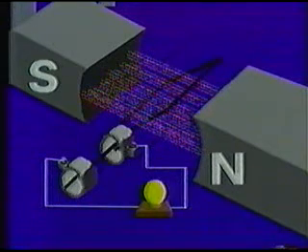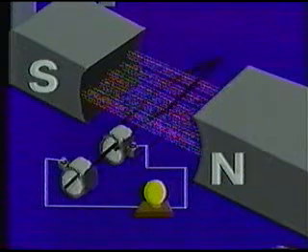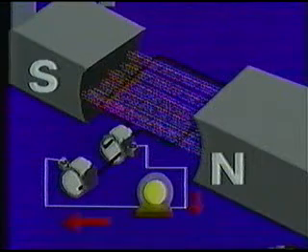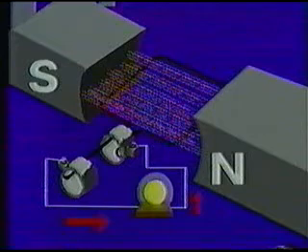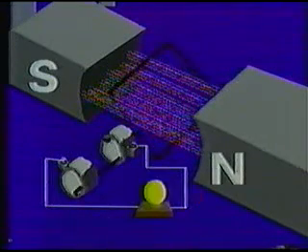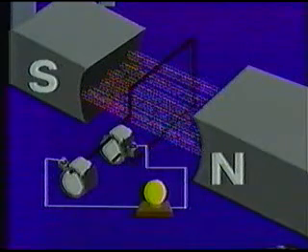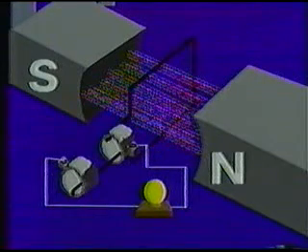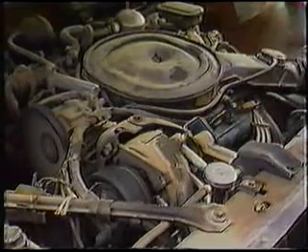The lines of flux that flow across a magnet project in the same direction. Unfortunately, because our conductor is rotating, it is cutting these lines in two different directions on each rotation. The result is that each time the conductor cuts the lines, a small voltage is induced. This voltage is alternating in direction because of the change in direction of the conductor relative to the lines of flux. This type of voltage is extracted from a device called an alternator, just like the one in your car.